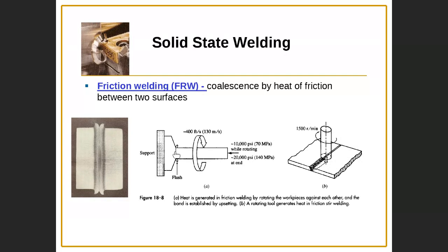This is a rotating shaft. This is not rotating. Then when you apply pressure, this one rotating, friction happens here in between. Due to the friction, temperature increases. Because we are applying pressure and friction here, increasing the temperature, a weld will happen between them. Atoms quickly migrate, and finally a bond will be created and you get the weld done, as you can see here in a photo. Let me show you another video for exactly this case.